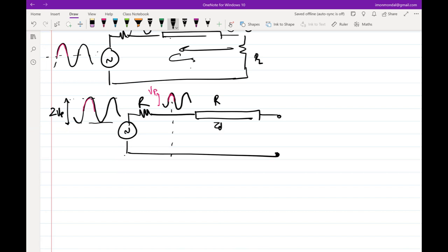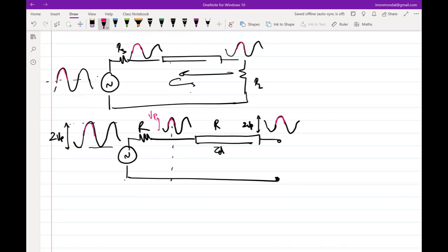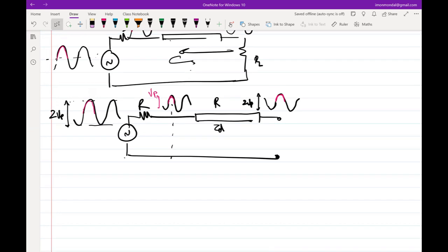After tau d, this is going to appear here, but there will again be a reflection, and the reflection will be identical to the forward going wave because gamma L is 1, right? So you are going to get a waveform which is delayed in time. Now the crest is here, it has moved in time. What will be the amplitude here? Think about it carefully. The forward going wave has an amplitude of Vp. The reflected wave also has an amplitude of Vp, and they are adding up in phase, right? It's not opposite phase. Reflection coefficient is +1. You are going to get 2 Vp here. But the reflected wave will have an amplitude of Vp, because this 2 Vp is the addition of reflection and incident.